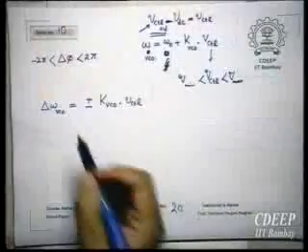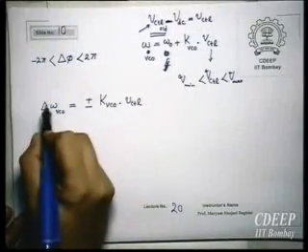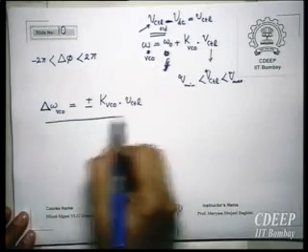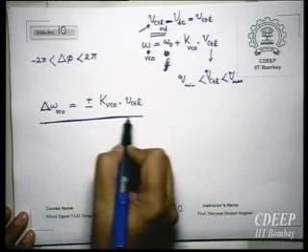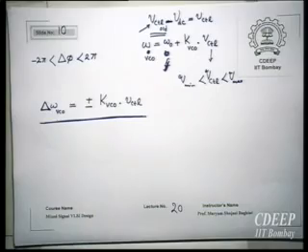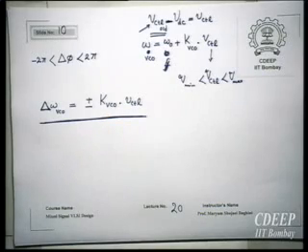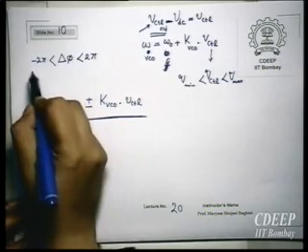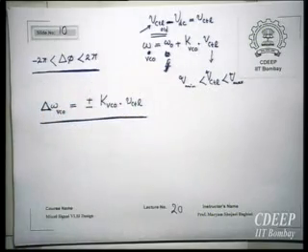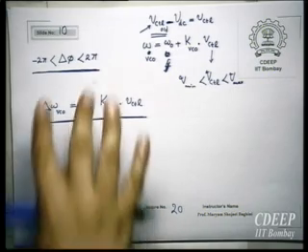So I just show it in this way. See, this is also the maximum value of variation in the frequency of VCO. It cannot generate more than this. Means that the maximum variation it can generate around omega 0 is this value, either in positive direction or negative direction. This is also the maximum phase difference that I can generate. 4 pi is same as 2 pi. Therefore, effectively, I have inherent limitation on the values.